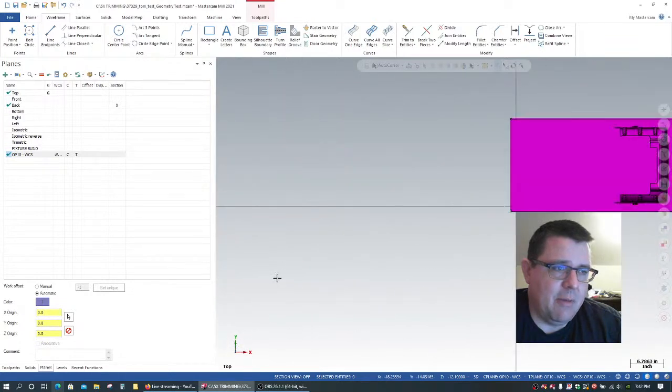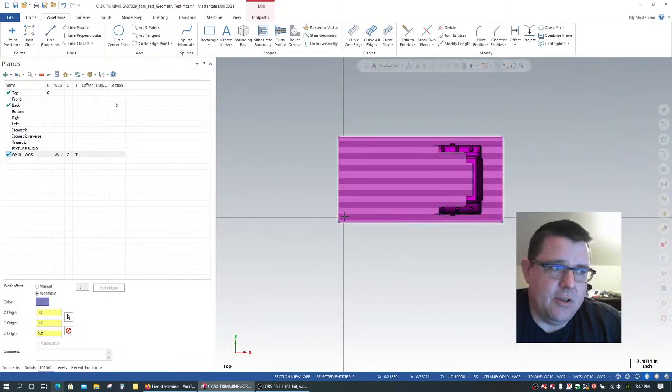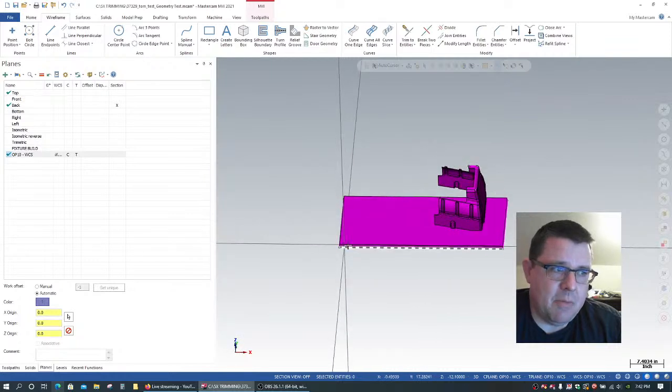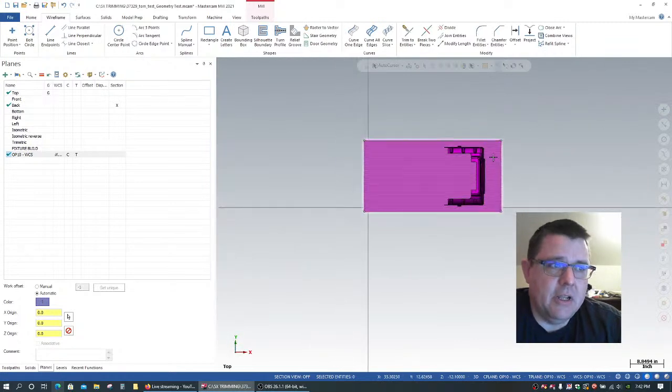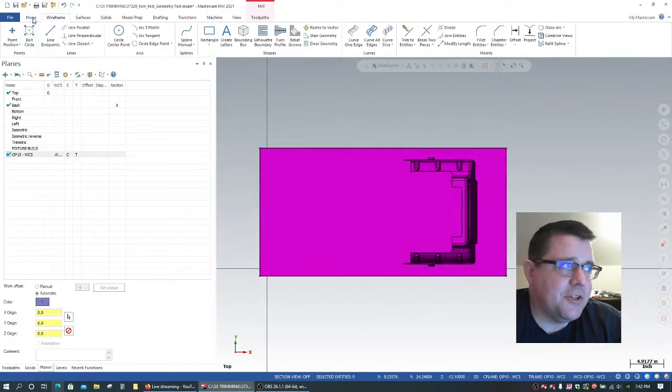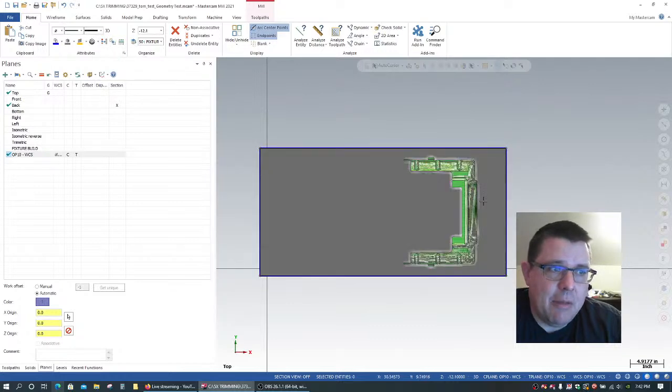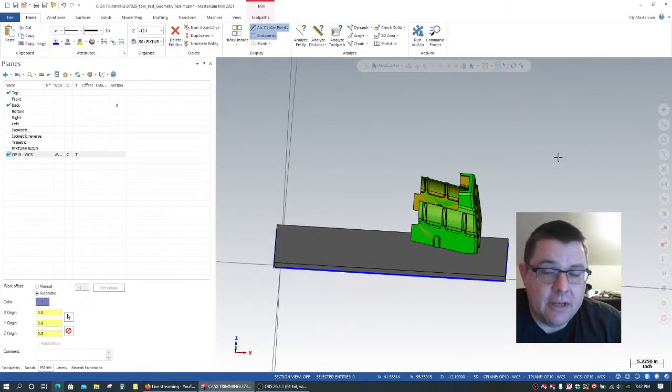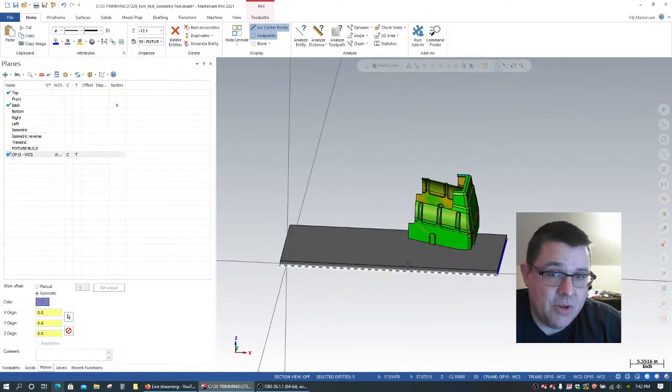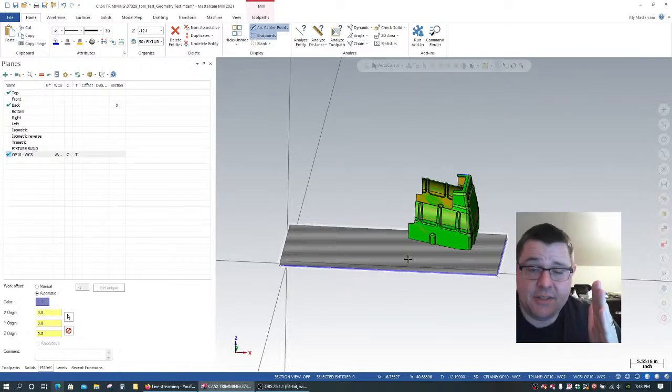If I look at it from the top view, the origin is in the lower left hand corner. It's at the bottom of my fixture plate, and this is how my part is sitting in 3D space. So if I analyzed my fixture and measured it with a dial indicator or something else, one of the tricks you can do is put like a 2-inch or 1-inch travel dial indicator inside a tool holder and set the length with the dial at 0, set the length of it to a known value, 5 inches, 5.5, 6, 7, 8 inches.